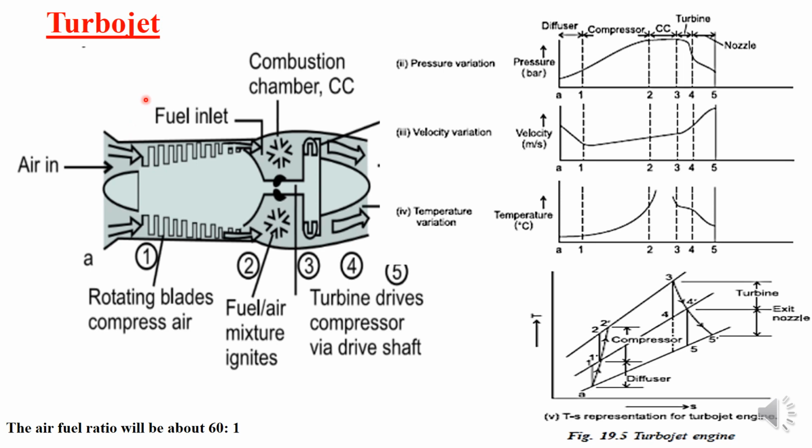So this action of partly compressing air by passing through the diffuser is called the ramming effect, ram effect or ram action, because it is having higher pressure than the atmospheric, and a ramming action can take place in the inlet of your compressor. That is denoted by A21. A21 represents your ramming effect, or a slight pressure rise from the atmospheric because of the diffuser section.